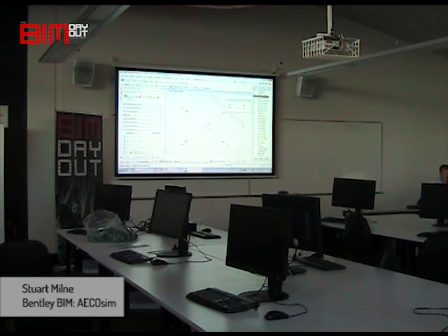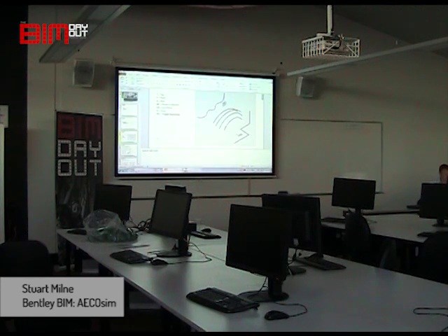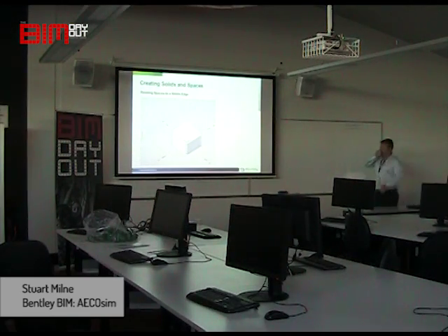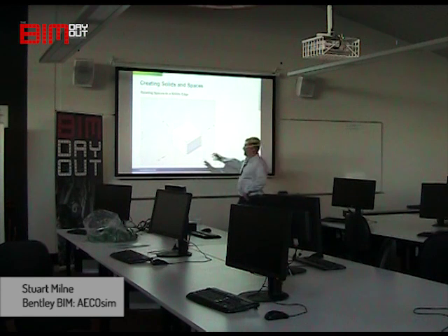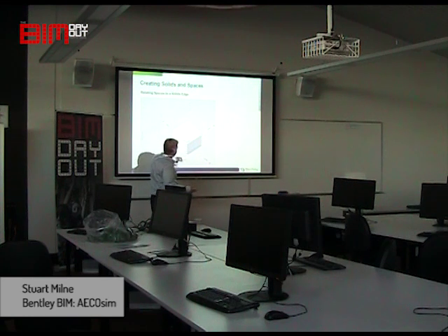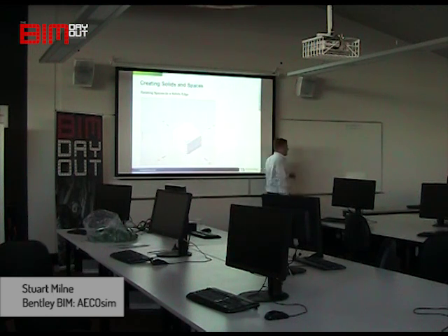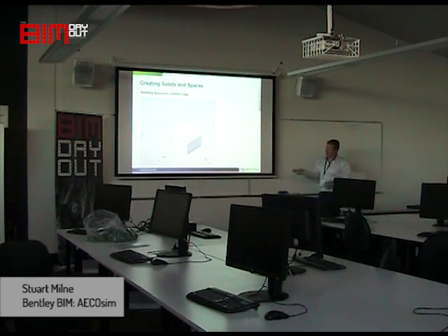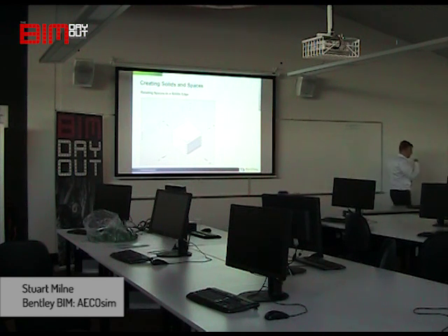Now, if you recall before, in our solid modeling dialog box, I'll explain to you what we're going to do. We'll create a very basic rectangular solid. We'll use a tool called the Spaces tool to create floor-like spaces within that solid. And then we'll start carving and pushing and pulling that solid and making sure those spaces react to the edges of that. A bit of a conceptual model, looking at areas of an envelope.